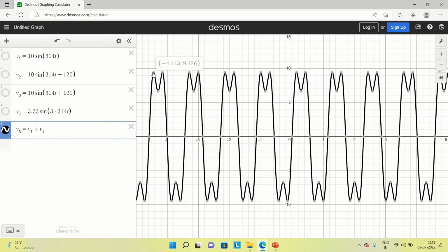So you can able to see this. Okay, so one wave shape change. Okay, then again second wave shape change, third wave shape change. Okay, so three changes in wave shape on one half cycle. So this is representing fundamental signal added with third harmonic.